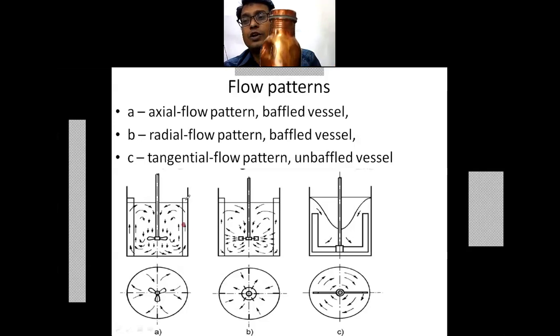If you look at this bottle, there are certain grooves which are provided, right? Similarly, these grooves are also designed in your agitation pot or the liquid pot. This serves the purpose of a baffle, and it creates turbulence also. As it creates turbulence, the tangential flow, or simply the swirling motion, is prevented. What swirling is, we will see afterwards. So the mixer is our basic agitation device.